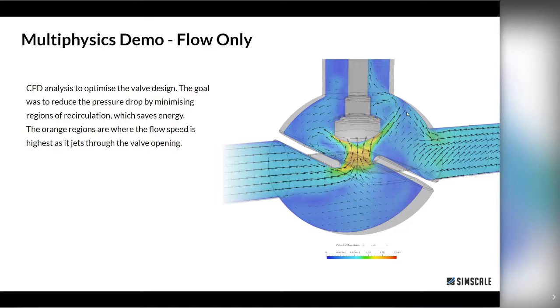And what we wanted to do is to reduce the amount of recirculation that we have in the valve. Unfortunately, with this design, you can see that there's definitely recirculation. So there's some at the bottom, even before the flow enters the main body, and then it all recirculates as it passes through and after the poppet. So we can do better there.